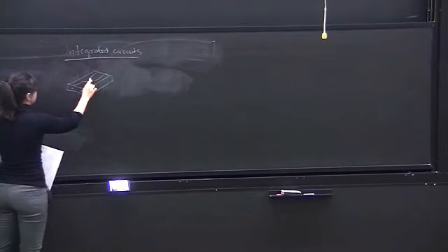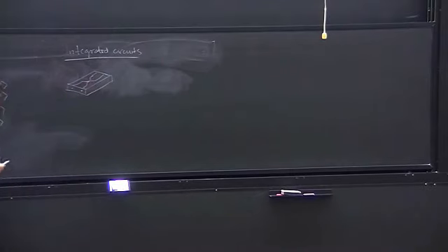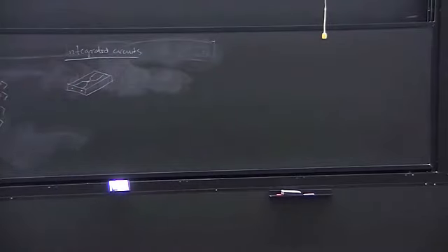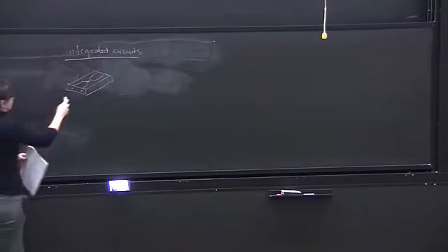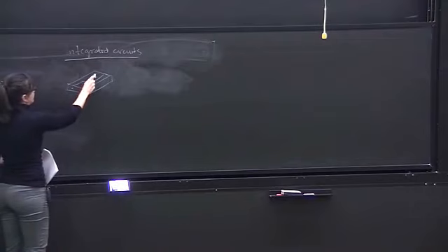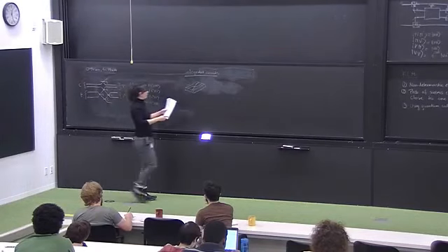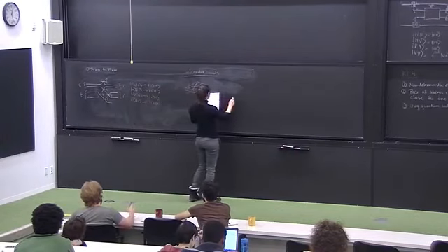And so now, instead of having a beam splitter like this, they control how much coupling there is between the modes just by bringing them closely together, and then they couple through what's called evanescent coupling. So the light leaks out of each mode, and then the two leaked bits interfere with each other. And so it's possible with some probability for the light to go from here and then come out this mode. And so then the corresponding integrated circuit that looks like this would be something like that.